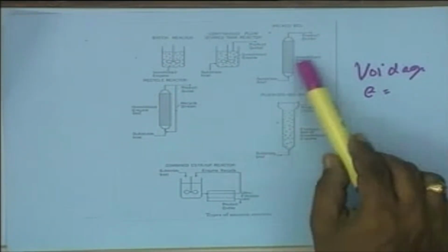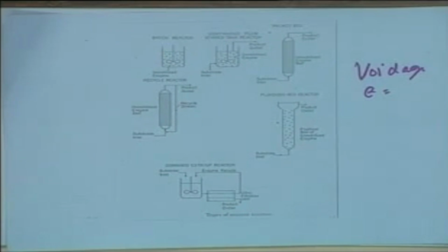In many situations, like in a packed bed, the heat and mass transfers may be very difficult, and particularly in reactions which are exothermic in nature, there might be a lot of local hot spots which can inactivate the enzyme. Fortunately, in enzyme catalyzed reactions, the reactions are not highly exothermic, they are usually isothermal, and therefore the problem of heat transfer is not so severe.